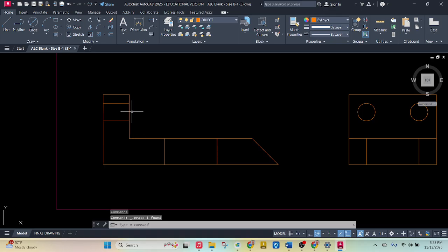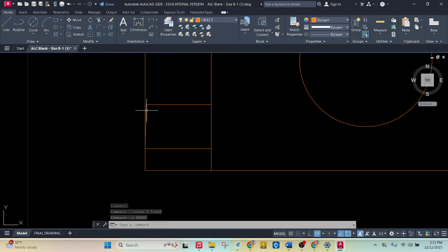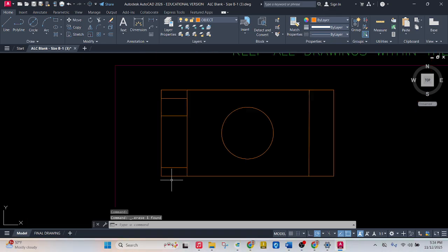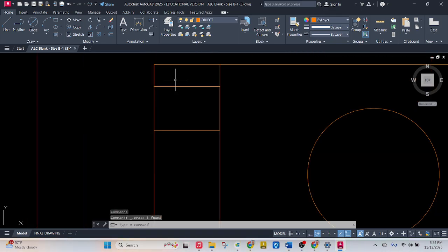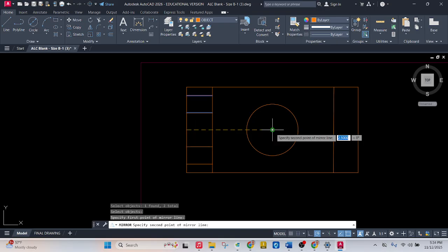You might have a lot of overlapping lines you can delete sometimes. That one wasn't. Like up here. Looks like I missed that by just a hair. Fix that really quick. In fact, I'm just going to mirror this over so it's the same. Mirror tool, here, here, right click, midpoint.